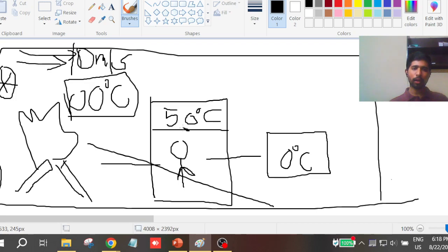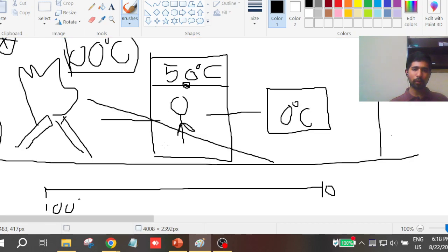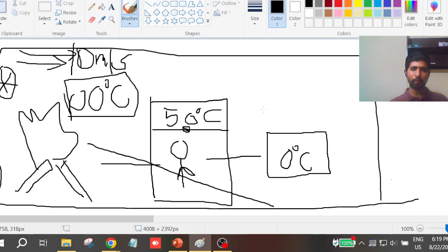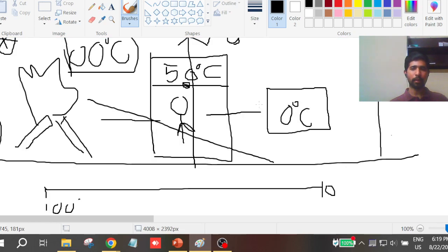Now usually what we do, if you assume that this is one grid point, even in FDM or FVM, whatever it is, and this is some other grid point, and you want to calculate the property at this face, generally we do averaging. But you have to understand, when there is convection happening, you cannot purely do an averaging of temperatures. That is what I wanted to mainly emphasize here.